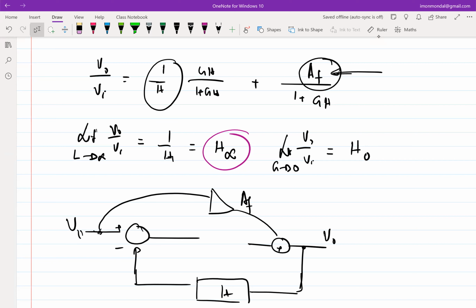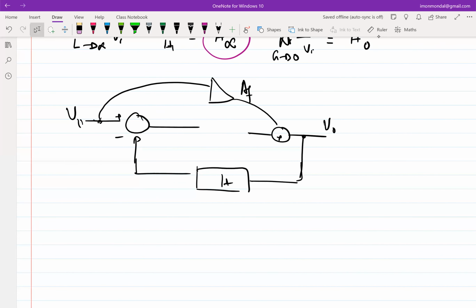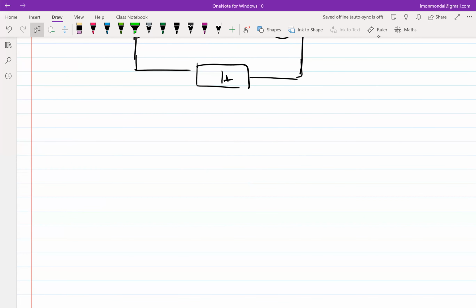So if I can figure out the loop gain, it should be straightforward because it's an open loop system. Finding a transfer function of an open loop system can be done more or less in one shot. You don't have to write multiple sets of linear equations and then calculate. So I know L easily. I know 1 over h or h infinity also easily, intuitively, because if the feedback network is working fine, V tends to 0, walk backwards, and whatever you get will be h infinity. I should also be able to find h naught easily, because if I can identify the forward path in the feedback network, all I need to do is set that to 0, and whatever output I get is h naught. Okay, fine. Since we are talking about these things in a very abstract way, let's take a concrete example and get cracking, right?